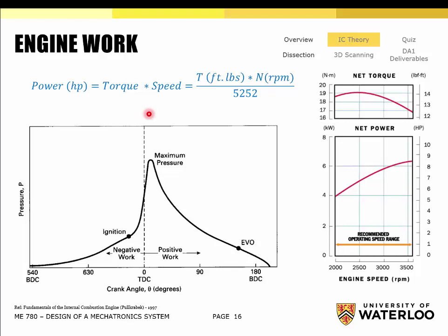So it's pretty much exactly what I want to hear, but not exactly. He said when it's at top dead center directly, the downward pushing force is not directly producing the work. It is pushing directly down, but it won't produce as much torque as when the piston is already on its way.